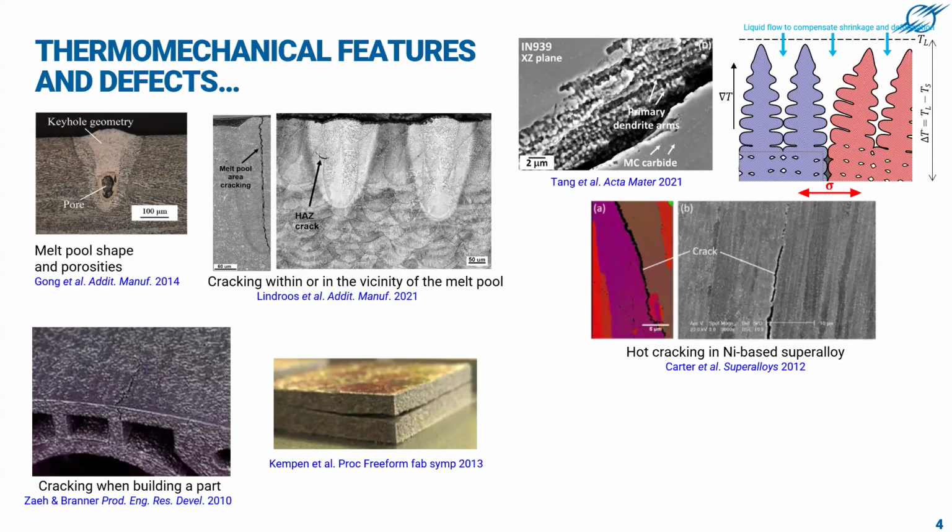I'll give you an example on this slide of some defects like porosities that you can have at the bottom of the, let's say, melt pool after solidification, due to fluid mechanics. Other examples are some cracking that you can find in the vicinity of the melt pool, like shown here.